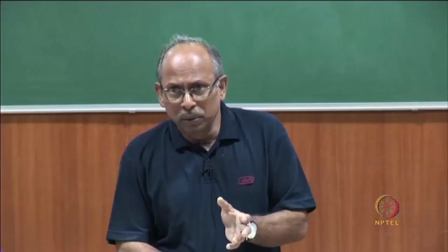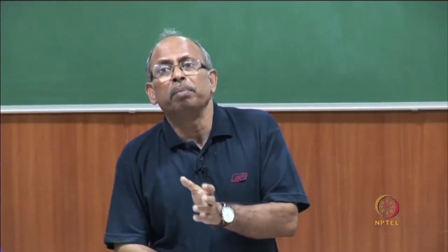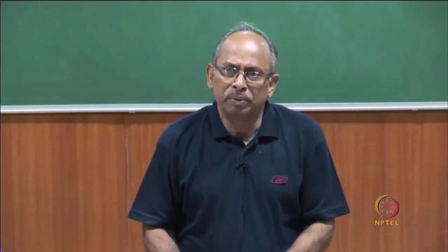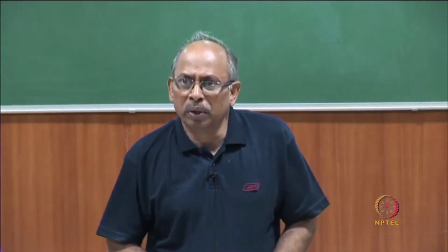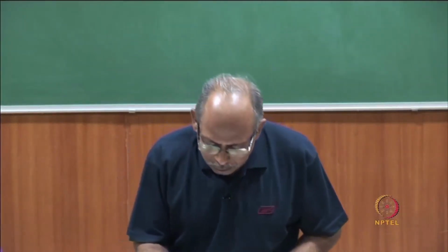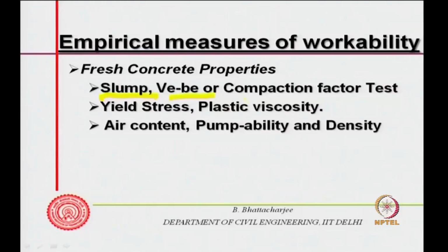Actually, at the moment we are not looking at them, and air content, pumpability, density, some are specific tests related to fresh concrete. We are not interested, but today we are interested more in slump, VB and compaction factor tests, which are very common empirical tests which are used. In fact, this is most common.